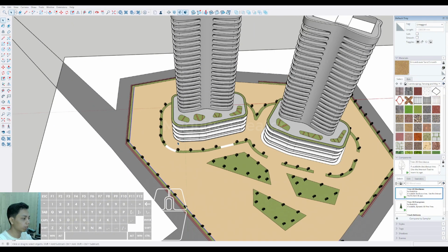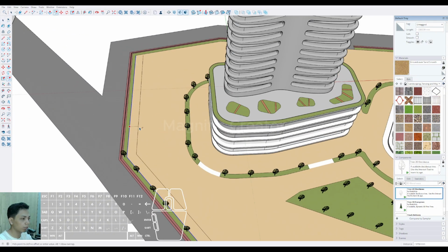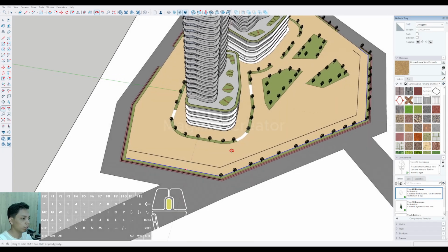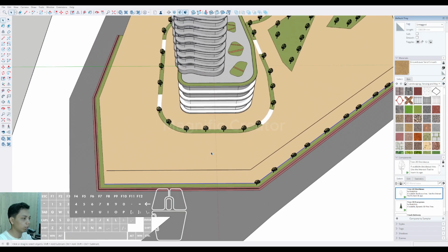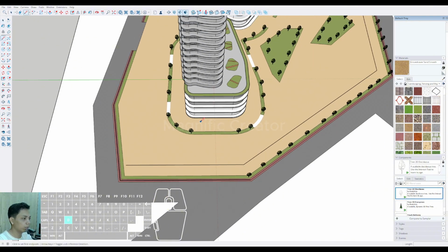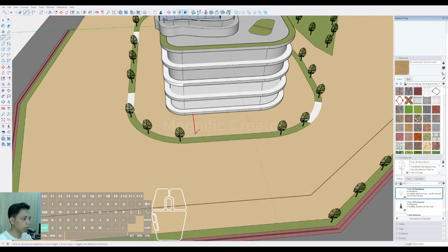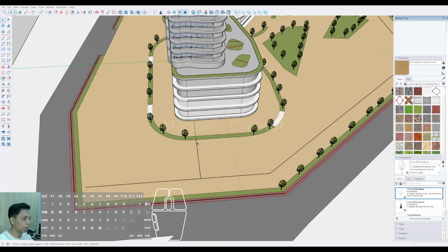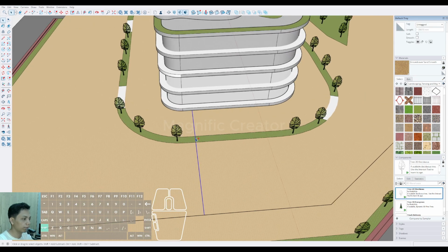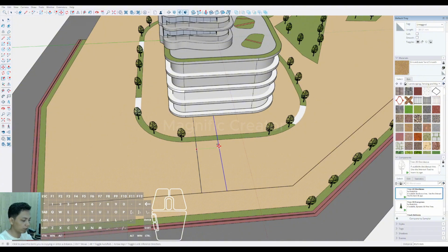Okay, so you have to offset it inside around, for the secondary road, maybe around 8 meter. Okay, just setting to the 8 meter, and we can consider the secondary road access. Select move, and we can type 8.